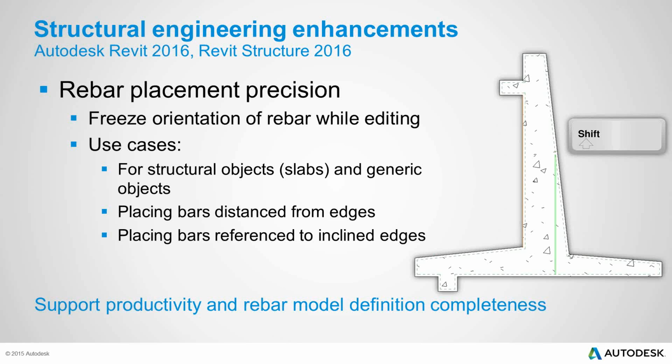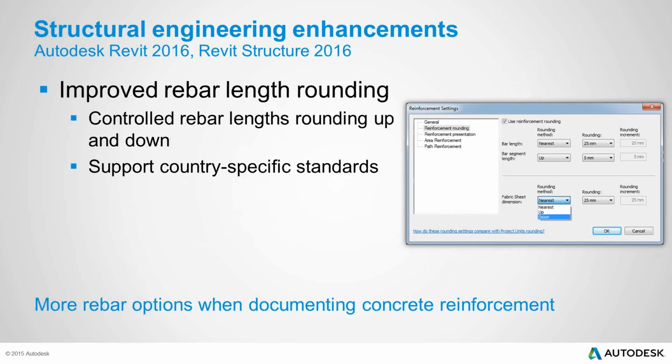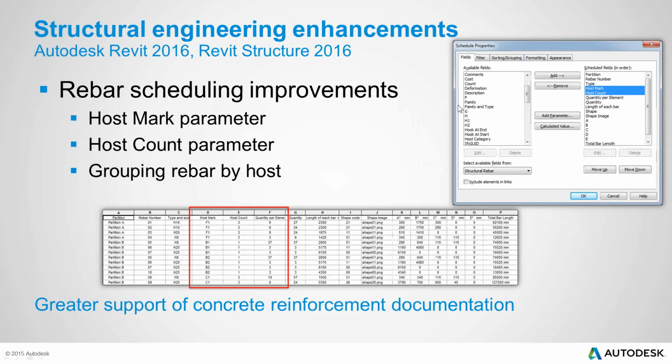So rebar enhancements, they keep going on and on. We're able to go in there and have rounding for rebar, which has been great. So now you don't have to have like 3/64ths of an inch on there. You can have it round up or round down to those extensions in there, which has just been a nice thing to have. I'll show you guys some of these things in a second. We have a lot of these things in here, and we'll find that in the settings in there. So I'll go to the settings in there and look at this.